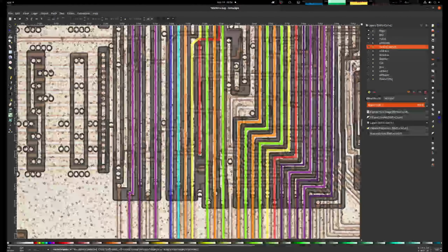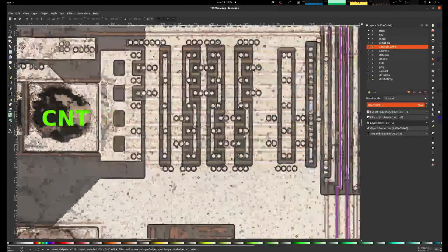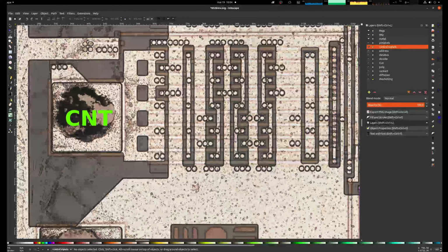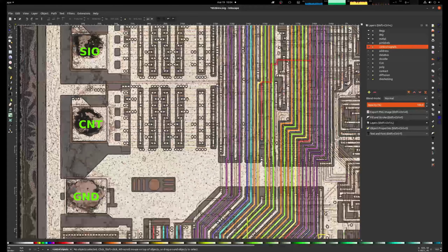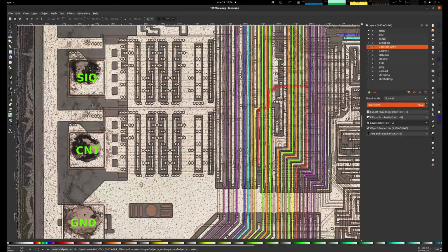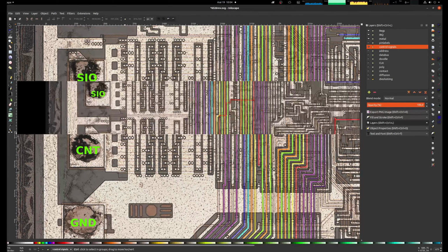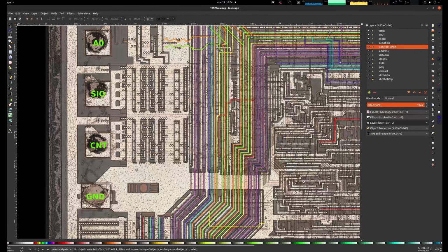And then it has another one here, and this is for the count pin, which also needs to be controlled. So this serial port works in that way that the data is put on the serial port pin, and then it is clocked with the count pin. And if it's an input, the device driving this chip needs to control these two lines.